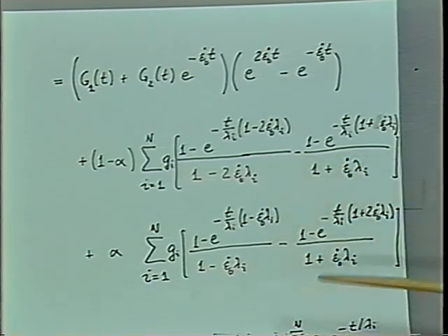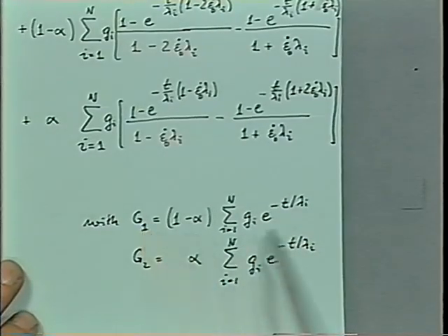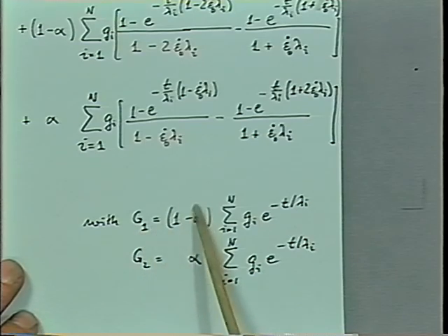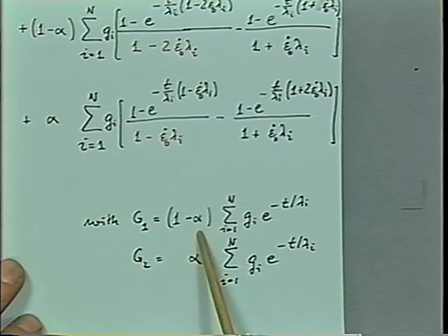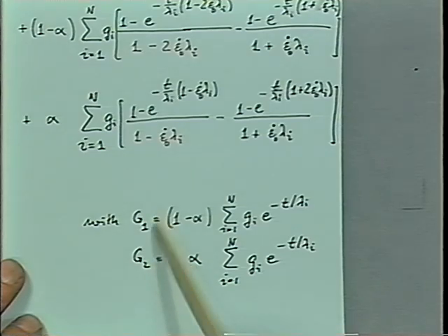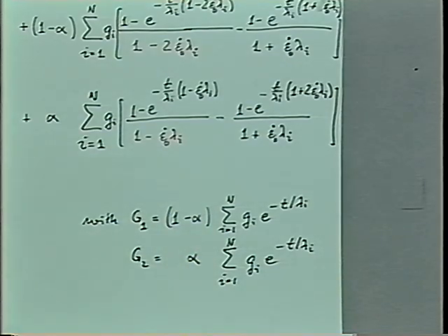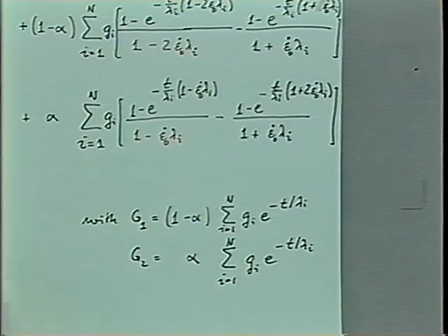In this case, I picked a relaxation modulus given by Maxwell modes. And for the first one, I put in a weight function, 1 minus alpha. And alpha would be very small. And the second contribution goes with the Cauchy strain tensor having alpha. So the sum of the two would eliminate this, and G1 plus G2 would be the relaxation modulus, which we use in linear viscoelasticity, just to make sure that we are satisfying the limiting behavior at very, very small strain.